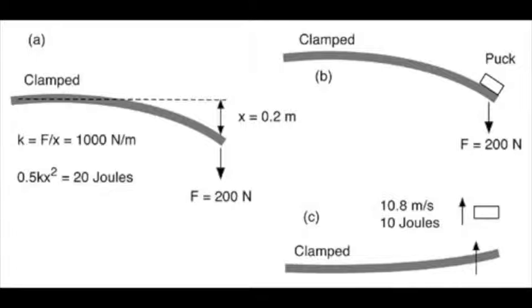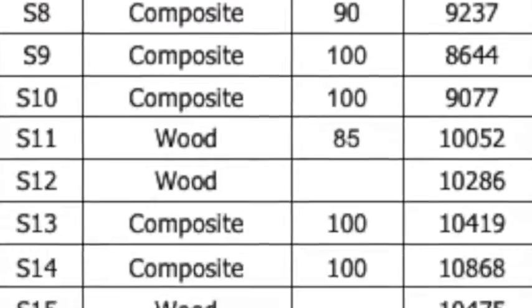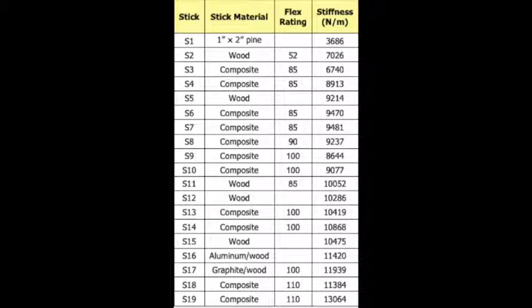If the stick has a high flex, then we know that k will be large. However, it is typically about 1,000 newtons per meter, which we will use for our example as well. Therefore, if the stick travels 0.2 meters, and the flex, or k value, is approximately 1,000 newtons per meter, the force will be 200 newtons. Here are some more examples of sticks. You can see that as the flex changes from wood to carbon fiber, the k value varies as well.